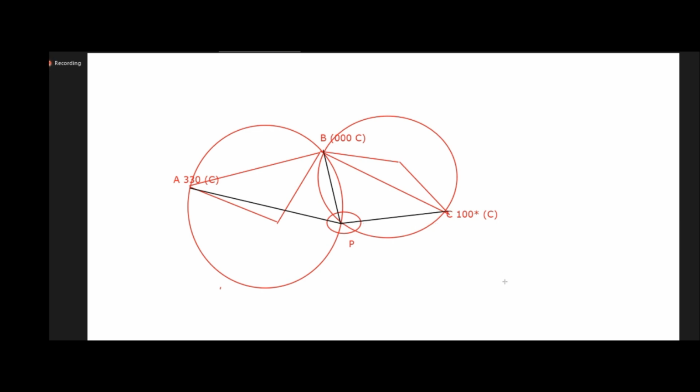And by parallel ruler, take the true bearing. It was 330, the compass bearing. From the P, put the parallel ruler, go to the compass rose and take the true bearing. And the true bearing here, 328, is the true. 328 degrees true, because you are taking it now by the compass rose. Okay, from the compass rose you will get the true.